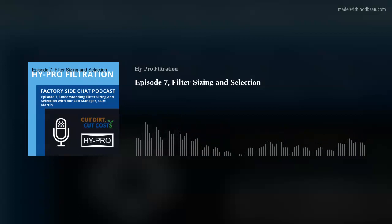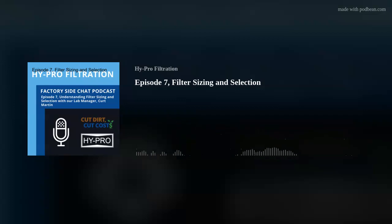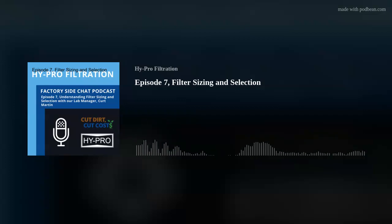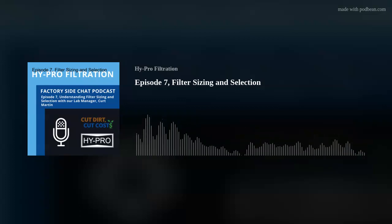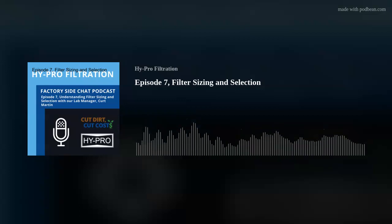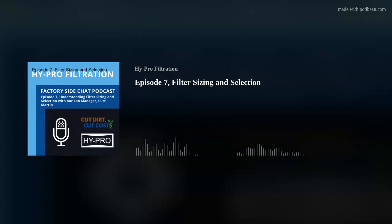So if this is an application that needs to be cleaned up really quickly, in hours or a day or two, obviously you want to start with the tighter filter, but they need to be prepared that they would most likely use quite a few filters quickly, depending on the cleanliness of the system. If it's a really dirty application and they're trying to get it down to a target ISO code really fast, that's a situation where you have to change filters quickly.